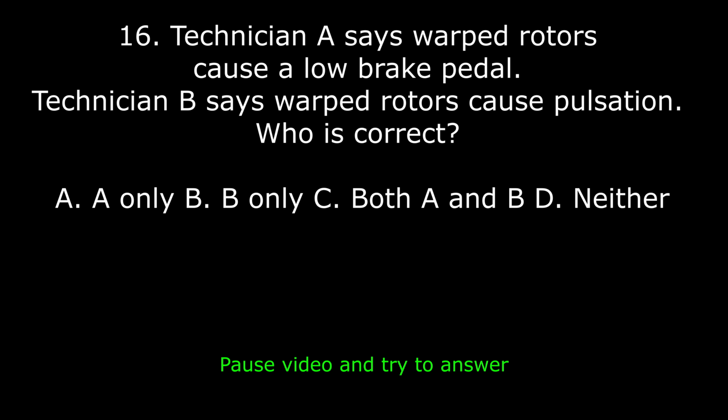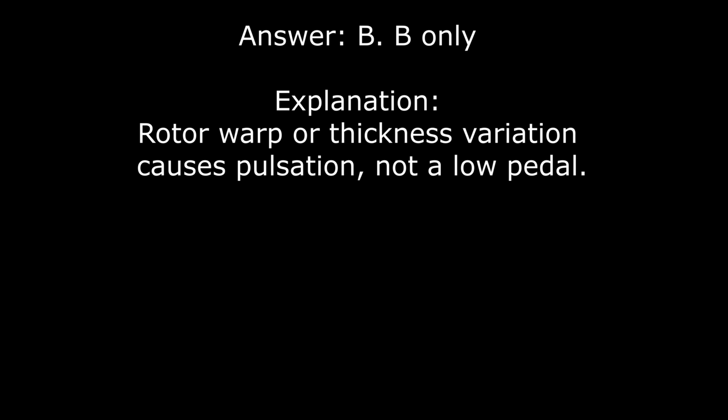16. Technician A says warped rotors cause a low brake pedal. Technician B says warped rotors cause pulsation. Who is correct? A. A only. B. B only. C. Both A and B. D. Neither. Answer. B. B only. Explanation. Rotor warp or thickness variation causes pulsation, not a low pedal.